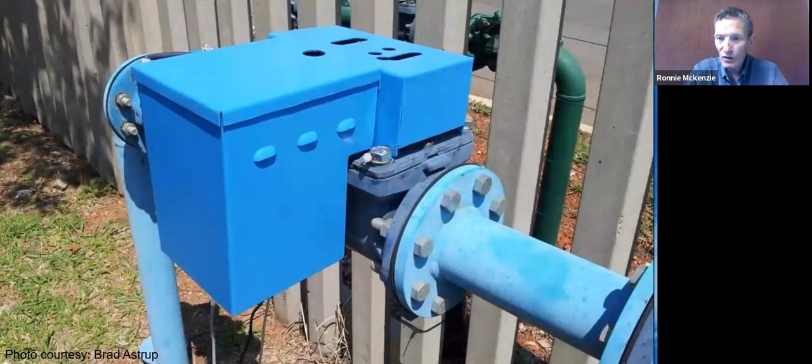We protect the loggers because they will get stolen. It's got a battery in it. Anything with a battery is fair game. So we normally stick our loggers into metal boxes, which protect them. And we get signal through. We find the metal doesn't really stop our GPRS signal going through the logger.